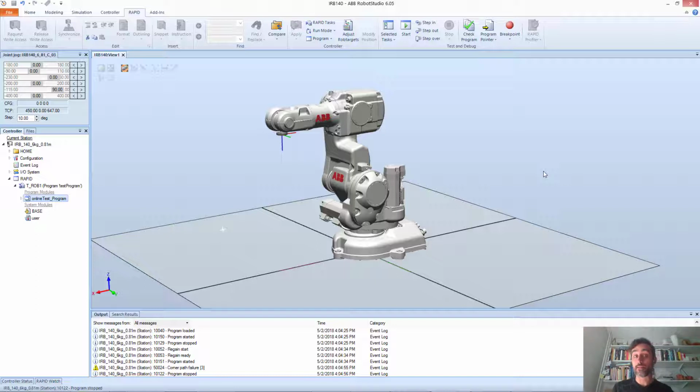What that means is that this robot as a device is visible to Machina in the local network, just as it would be if I connected my laptop through an Ethernet cable to a physical ABB robot, or if I connected to the robot via a local network somewhere. So I can use this simulation in RobotStudio as a local connection to Machina, and then I can stream stuff in real time as if it was the physical robot. This is not the case for other brands of robots, so this is very nice from ABB in particular.